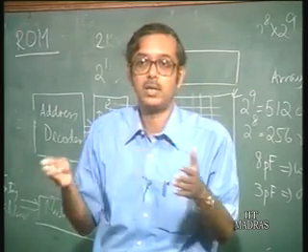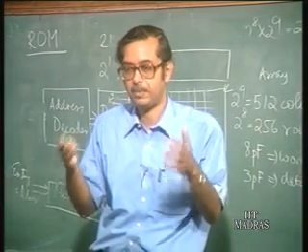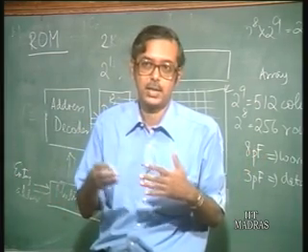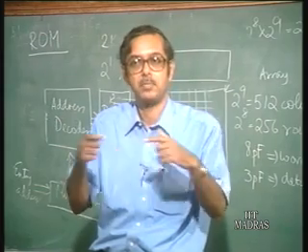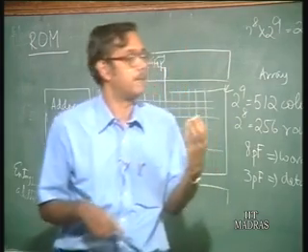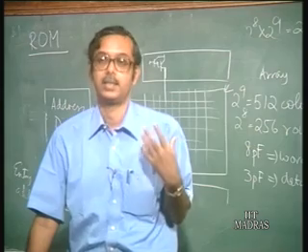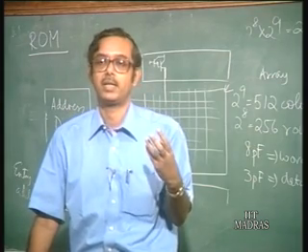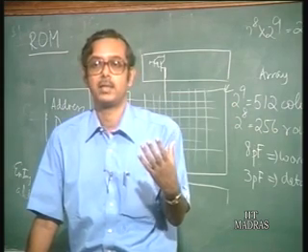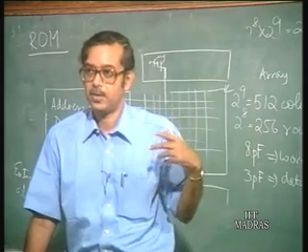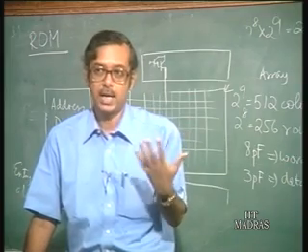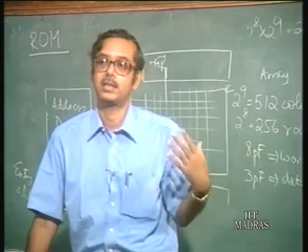If you want to fabricate an equivalent MOS transistor driving the same current, the size would be huge. Whereas a bipolar transistor can provide a lot of current. At the same time, the transconductance of a bipolar transistor is much higher than that of a MOSFET, because a bipolar transistor follows an exponential relationship between input and output. That is, the output current is proportional to the exponential of the input, exp(VBE/VT). So, only a small change in the input voltage is required to make a very large change in output current. Whereas in the case of MOS transistors, it is a square law relationship.